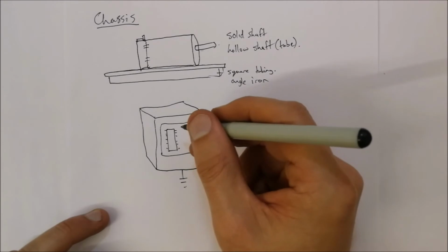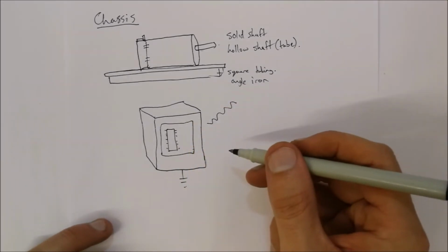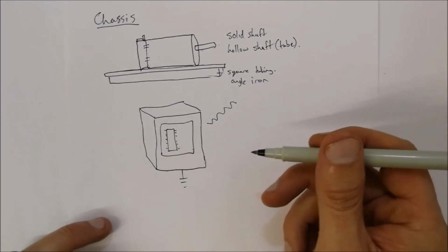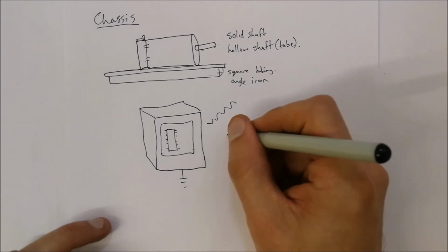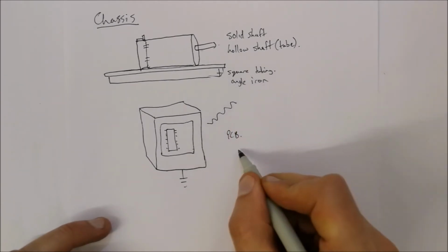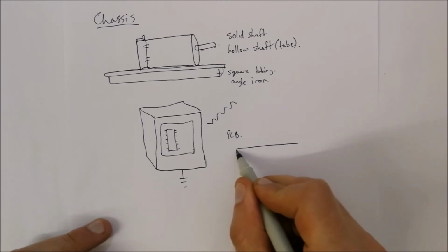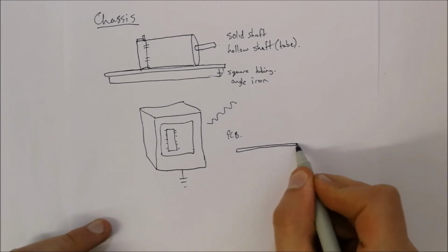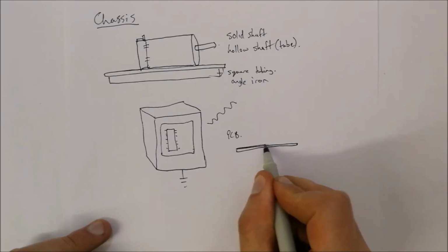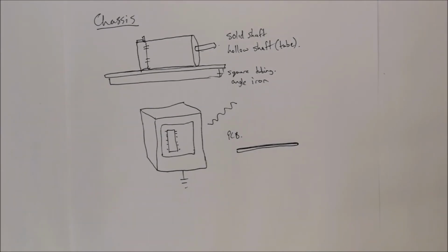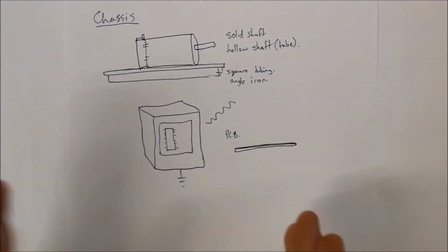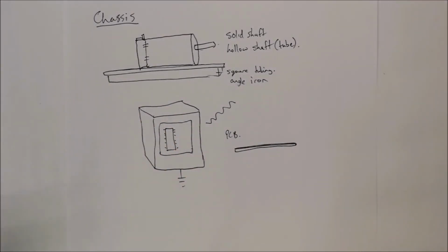So you could find that it might be good enough to use your printed circuit board materials, or the PCB materials. If you keep in mind that is a sheet of fiberglass, probably about 1 millimeter thick, and then it's got a very thin layer of copper on top of it, that you're able to etch to make your printed circuit boards. So you might be able to take that and place it into this specific cube shape, and you're able to solder it together, and that will create this Faraday cage around your circuitry.